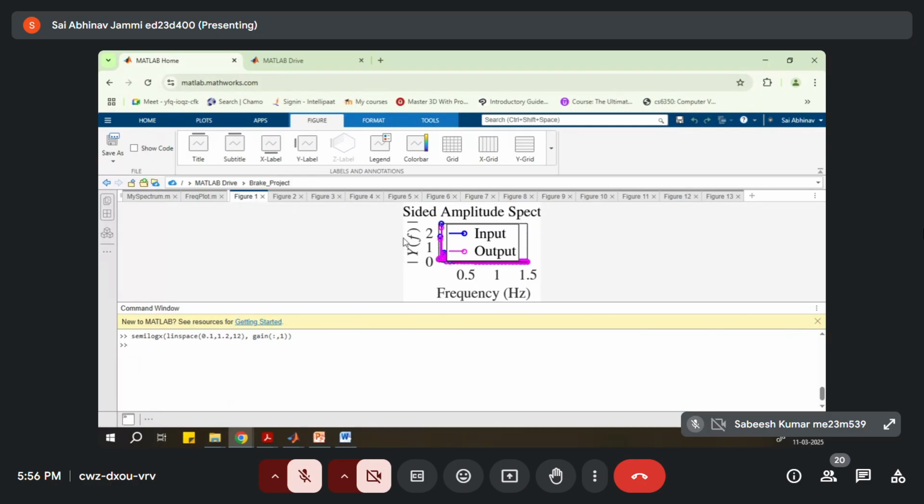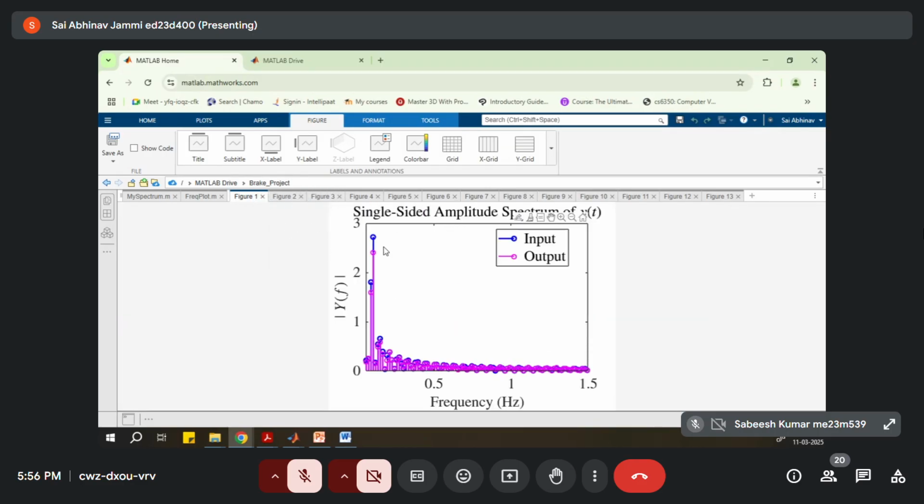So from the spectrum, for the Fourier transform, we obtain the peaks for each of the frequencies, and then we get the gain for our Bode plot, and the Bode plot will tell us whether it is a first order system or a second order system. Is that clear?